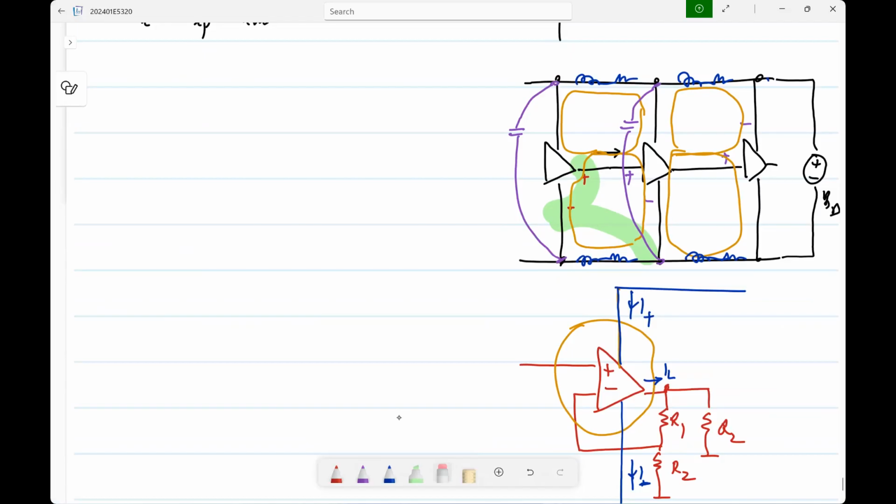So it is to avoid this that we have fully differential circuitry, right? We know that voltage is measured as a difference of voltages at two nodes. So for every signal, you just dedicate two wires, instead of saying one wire, I will use it common. There is some merit to using a common wire. It is economical: for every signal you use only one node, plus the reference node. Whereas fully differential is uneconomical, because for every signal you are using two nodes. But you don't have this problem of sharing the common reference node.